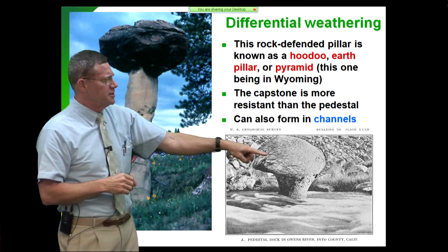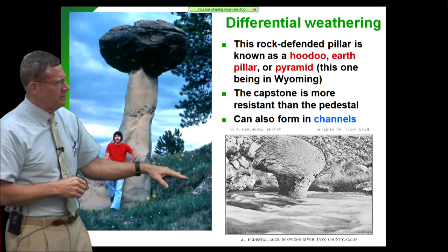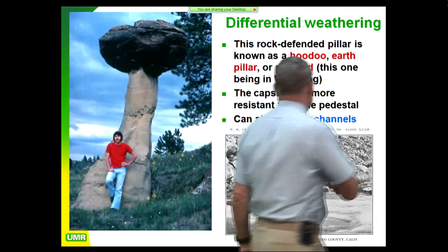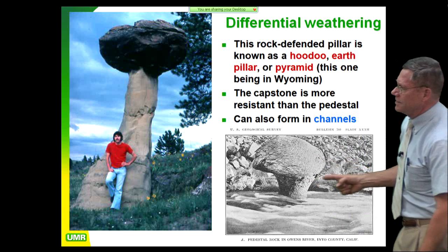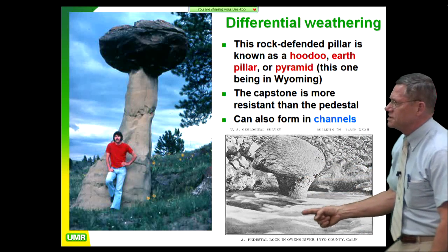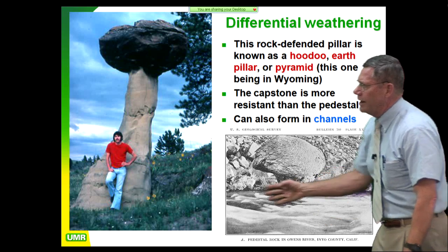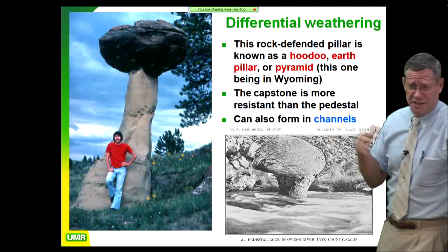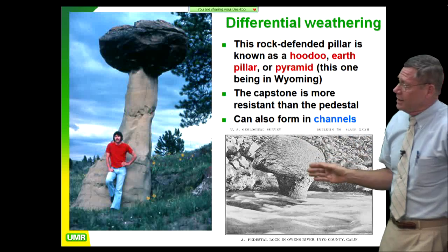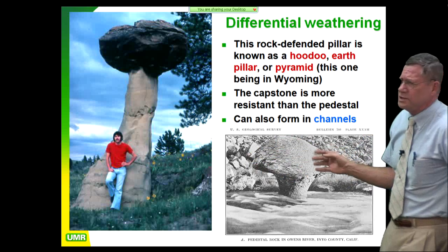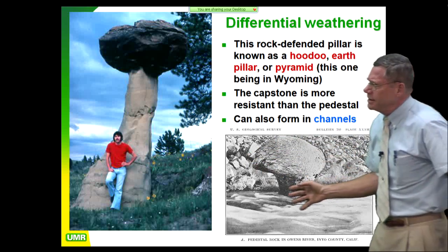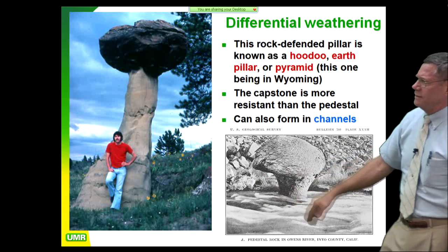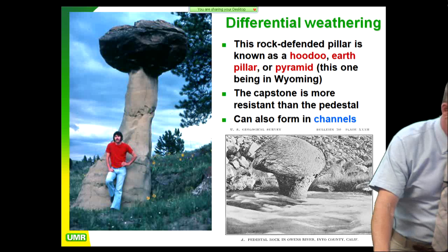This is one over in Owens Gorge in the Bishop Tuff. And this is just from the water going by on the Owens River. And the water is actually traveling in this direction. The high water line is, this is low water, there's high water. And the water has a tremendous abrasion because of the silt load. Silt has as much abrasion as sandpaper. And so this tuff here, which is a relatively homogeneous volcanic ash, it's experienced differential erosion from the turbidity of the channel flow. And that makes good sense.